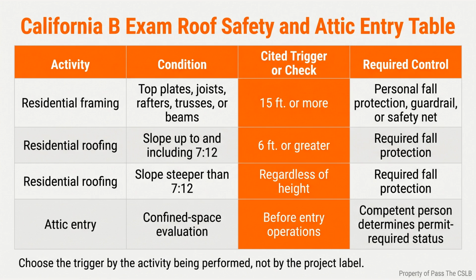The strongest memory aid is still the simplest. A vented roof needs intake, airway, and exhaust. An unvented roof needs a complete thermal and moisture control assembly. The word unvented never means unmanaged.